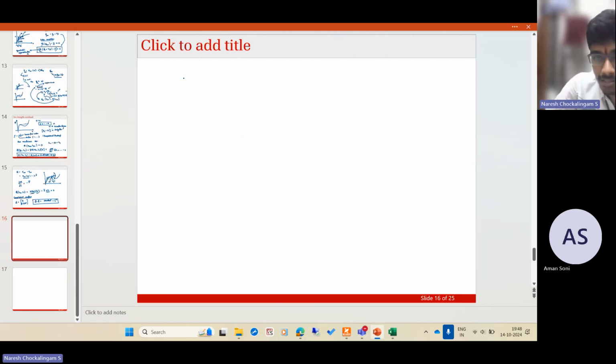So this is again very similar to the Newton-Raphson. The update step is the same. Xk plus 1 is xk plus u. Similarly, here we are not only updating the displacements, but also updating the load. Lambda k plus 1 is lambda k plus delta lambda. Now we have to find u and delta lambda. How do we find u?